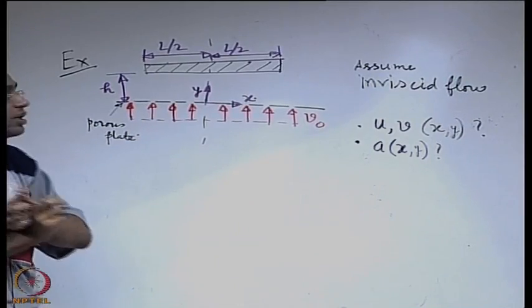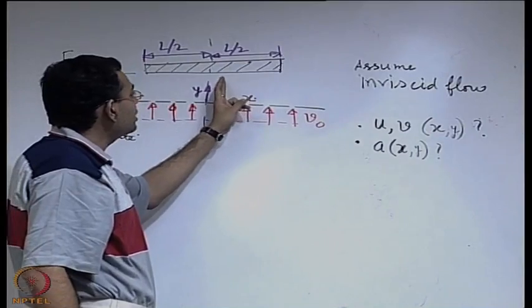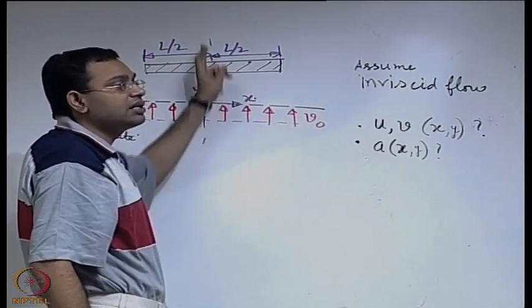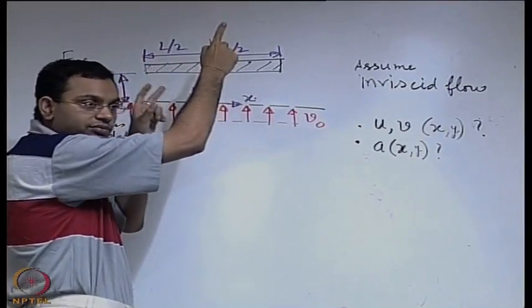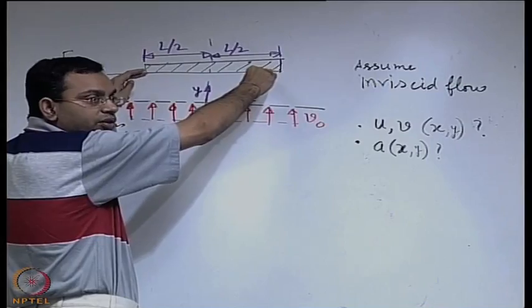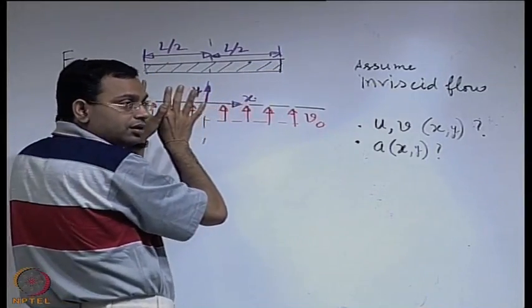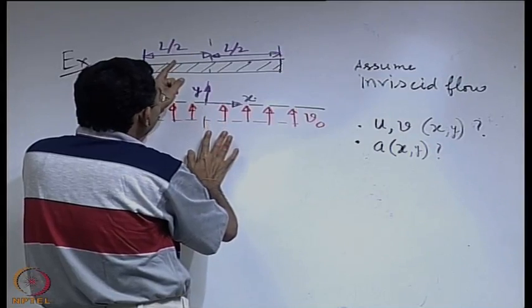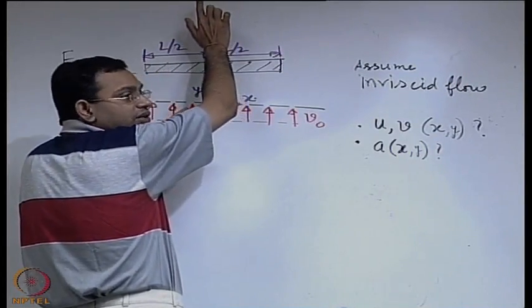No, because no slip ensures that it has no tangential component, but it simply is a no penetration condition, because it cannot just penetrate through the wall and go out, because it is just a fully covered solid wall. So no matter whether it is slip or no slip, you cannot actually penetrate it and go out along y.